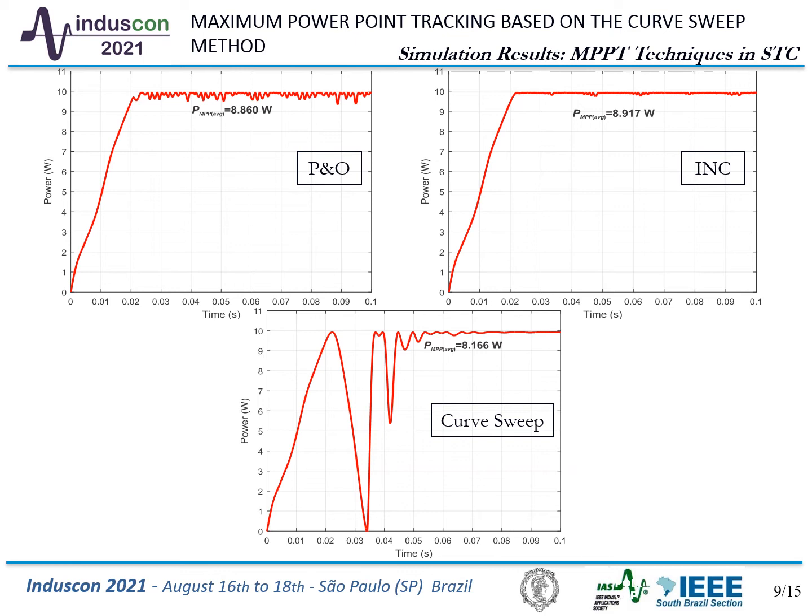It is observed that the average power for a time window of 0.1 second is the least for the proposed method because it is necessary to sweep the entire current versus voltage characteristic, which takes longer to achieve the maximum power, unlike P&O and INC. However, both P&O and INC present an oscillatory behavior, as we can see in the provided results.